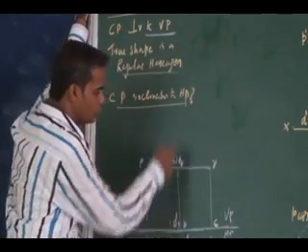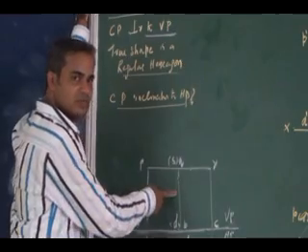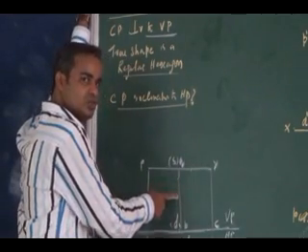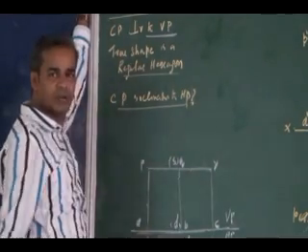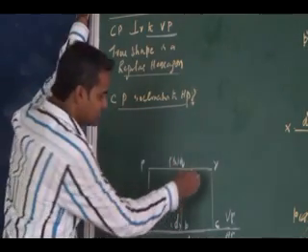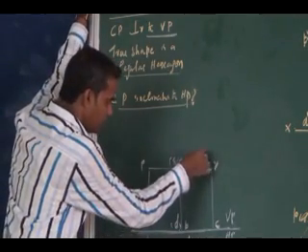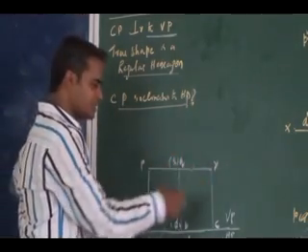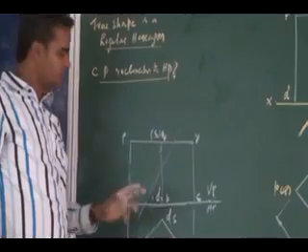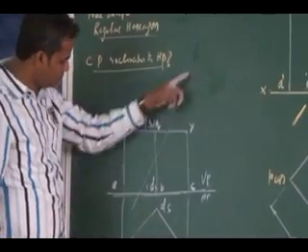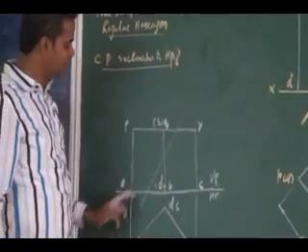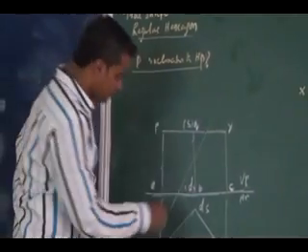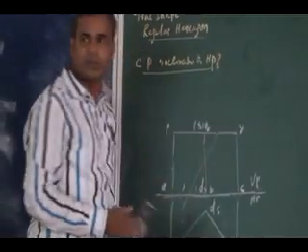That is, I have 2 vertical edges coinciding in the middle. So if it passes through those vertical edges, I will get 2 more cutting points. So totally I should get 6 cutting points. So my cutting plane should pass through the 2 bases and the middle 2 vertical edges. If it cuts like this, I will get 6 cutting points, it is confirmed.